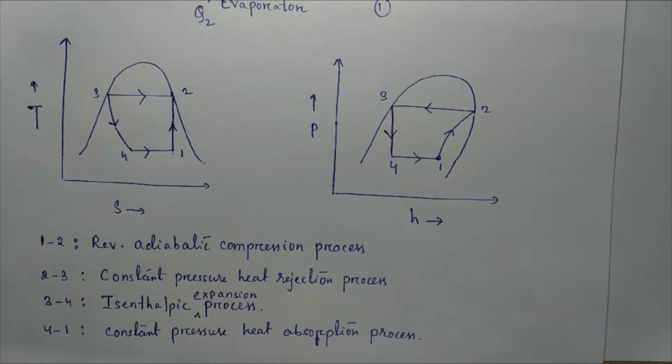An evaporator consists of coils or pipes, because this is also a kind of heat exchanger in which the liquid-vapor refrigerant at low pressure and temperature is evaporated and changed into vapor refrigerant at low pressure and temperature. In the evaporating process, the liquid-vapor refrigerant absorbs its latent heat of vaporization from the medium which is to be cooled. Right?